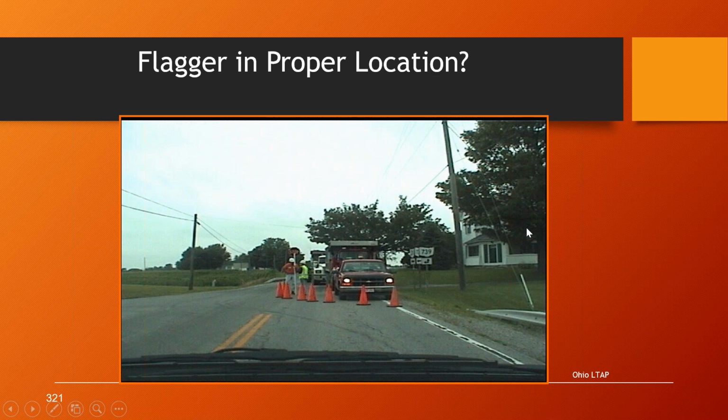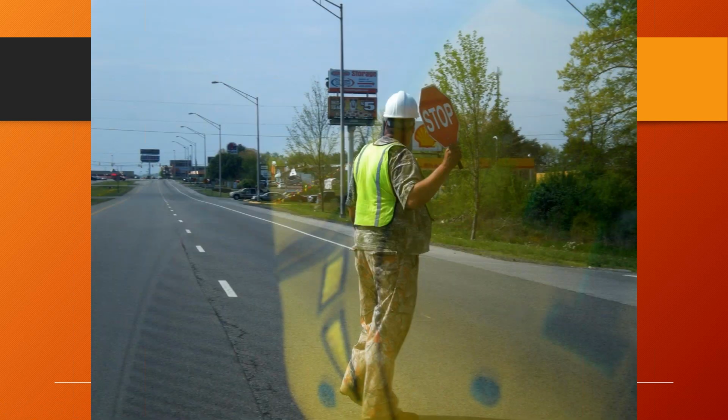And then here's a picture of the flagger standing up here by where the work is actually taking place in the middle of the road. So we don't want that to be the case. He should be well in advance of the work taking place. Then here's a flagger standing in the middle of the road with his back to traffic. No cones that are visible. So this is definitely not how we want you to do it.